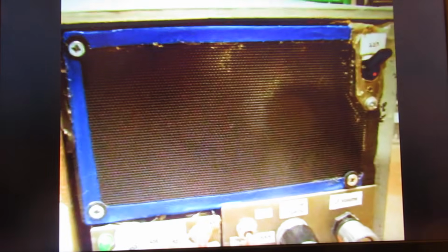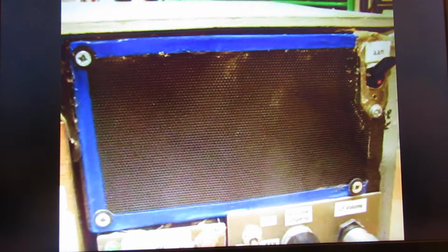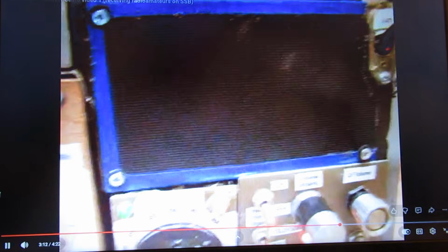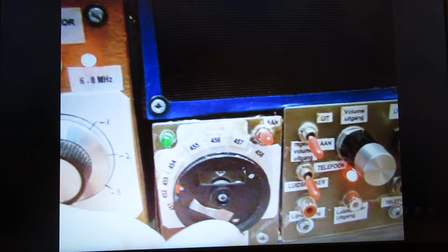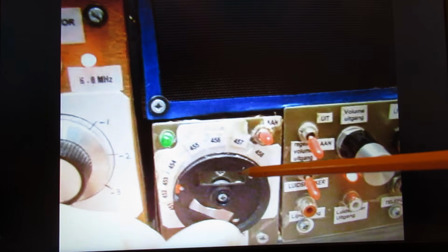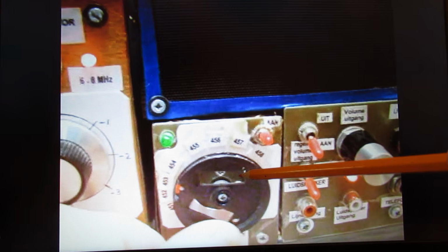And you can hear them now. And I now want to demonstrate the different functions by tuning all the knobs. It's very important to tell that you can insert that beat frequency oscillator frequency somewhere inside the intermediate frequency amplifier.